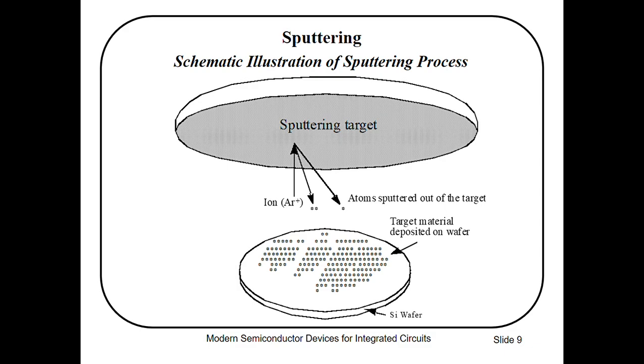During deposition, the chamber is first evacuated of air and then a low pressure amount of sputtering gas, typically argon, is admitted into the chamber. Applying an inter-electrode voltage ionizes the argon gas and creates a plasma between the plates.